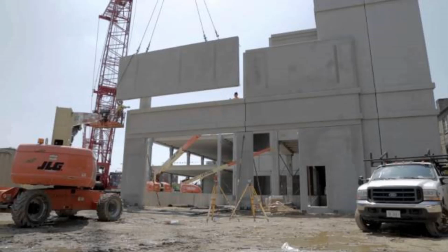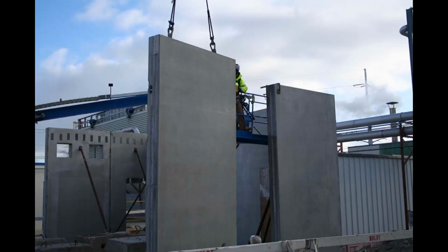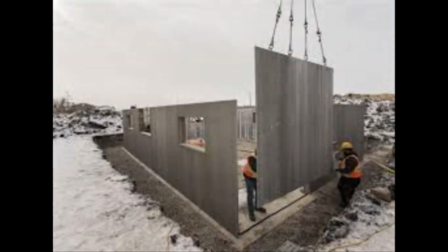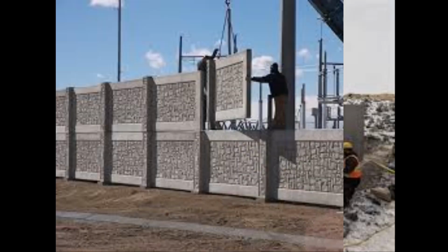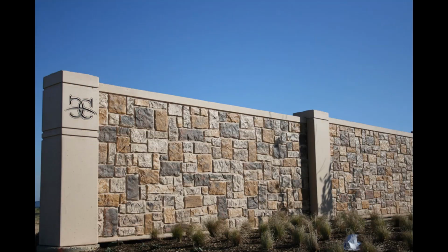Precast concrete insulated sandwich wall panels have gained popularity over the years. The reasons for their increased use in place of more traditional materials include speed of erection. It can be done very, very quickly. Cold weather doesn't come into play, and it's shipped to the site as needed. Another reason is design flexibility. You can have a lot of finishes and patterns, including inset brick, stone, and abrasive blasting.